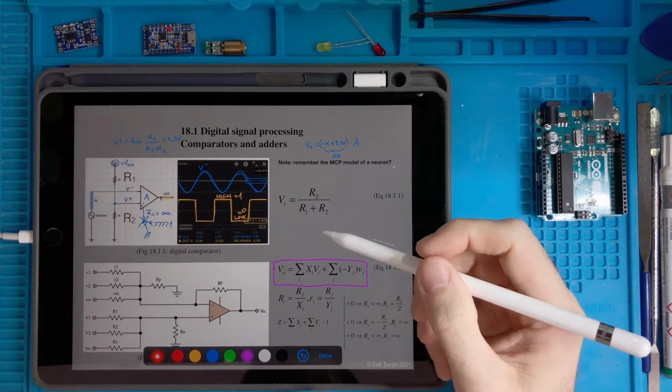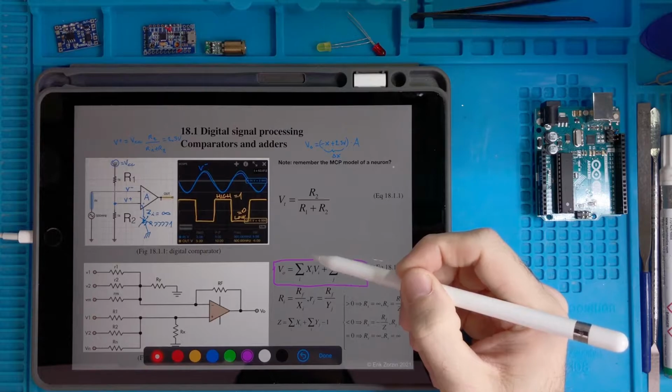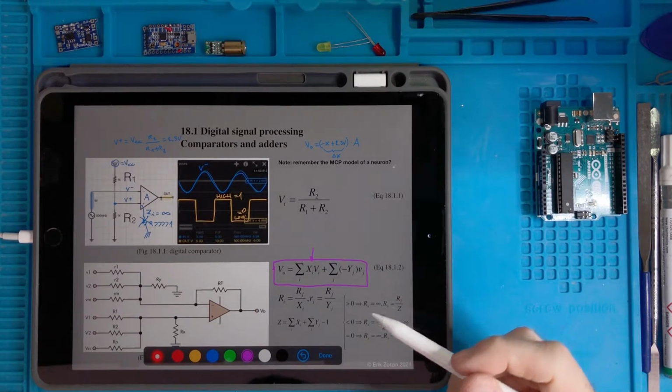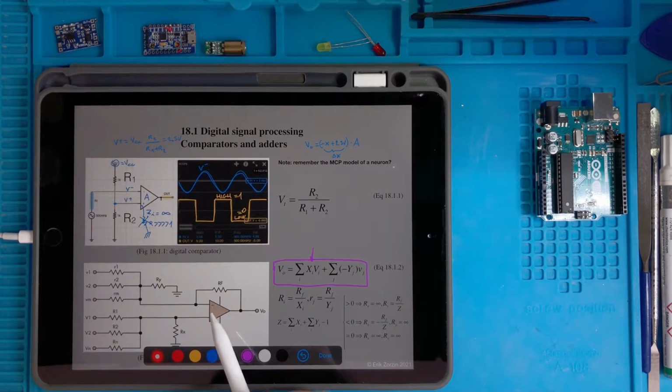Sorry, actually X are the weights, V is the voltage, and we have voltages applied to the minus and to the plus input, so the voltages can be summated or subtracted, so the weights can be positive or negative. This gives you an idea that if you have a differential amplifier, you can create a summating node having positive, zero and negative weights. With this you will be able to reconstruct the logic gates that we have studied a while ago.